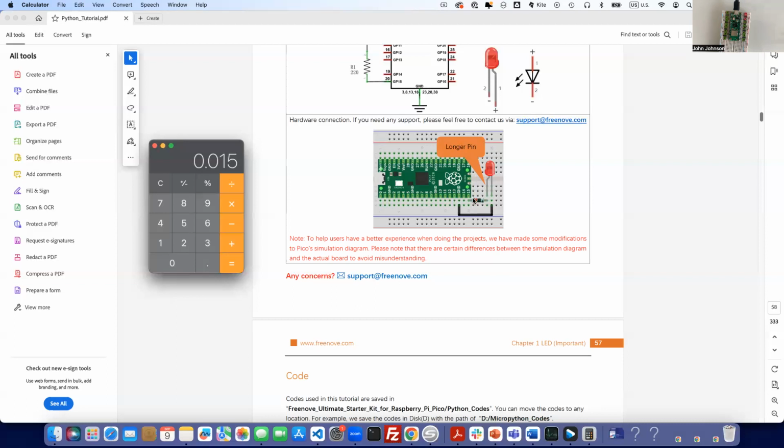From here, the long pin, we go to the resistor, and it goes back to power. So that's how everything is connected here. Because we've plugged in here, all these are on the same one, so it connects to the negative pin. And then it goes through here, the positive pin comes out, and everything here is connected. So it hits the resistor, and it connects over to here, where it goes again to pin 15.